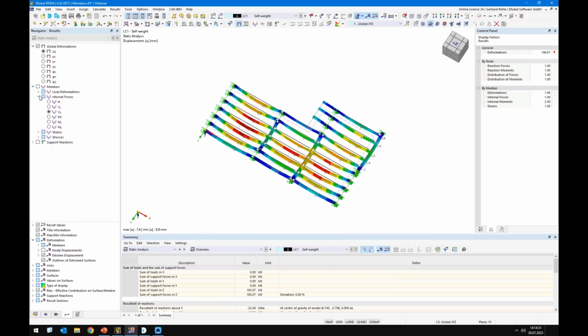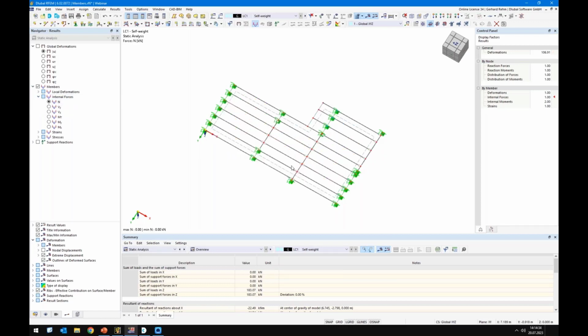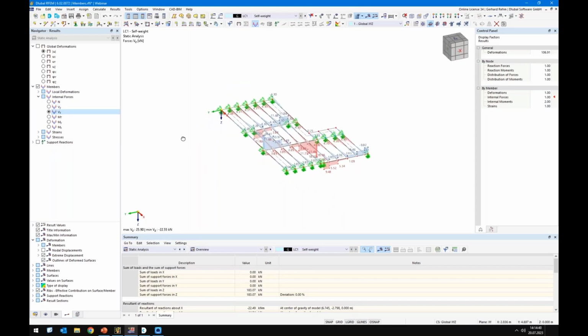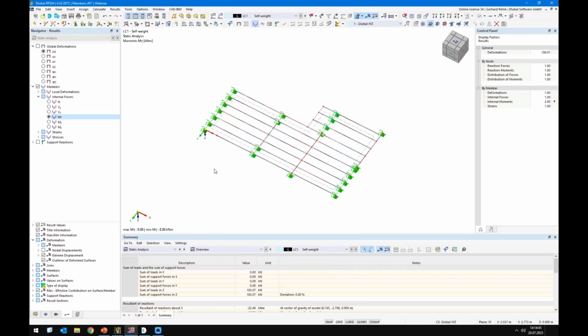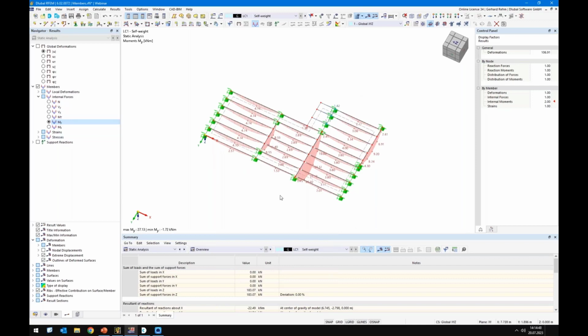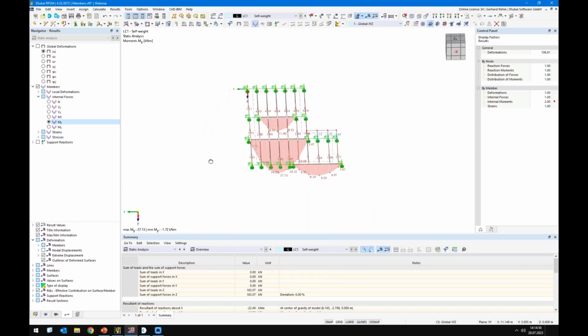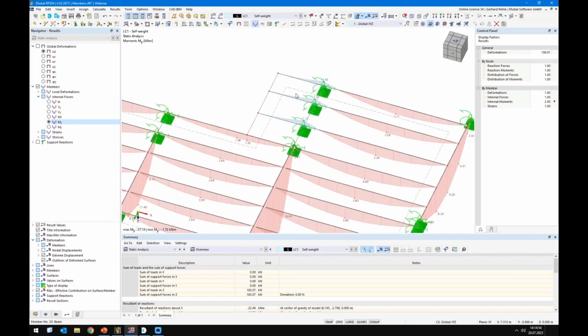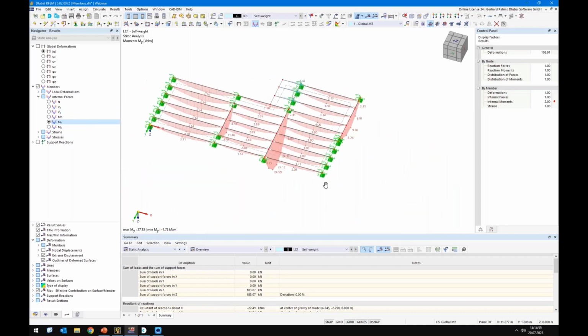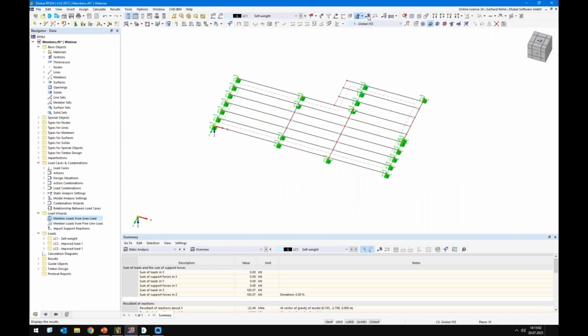Let's switch over to internal forces. So we should have no normal forces inside, no shear forces in Y direction, only in Z direction. That makes sense. And no torsional moments, that's also good. Bending moments look like for every one span beam, that's okay. Here we have our hogging moment, which is also fine on this cantilever. Yeah, okay, looks good so far, and now we can start to think about the design.